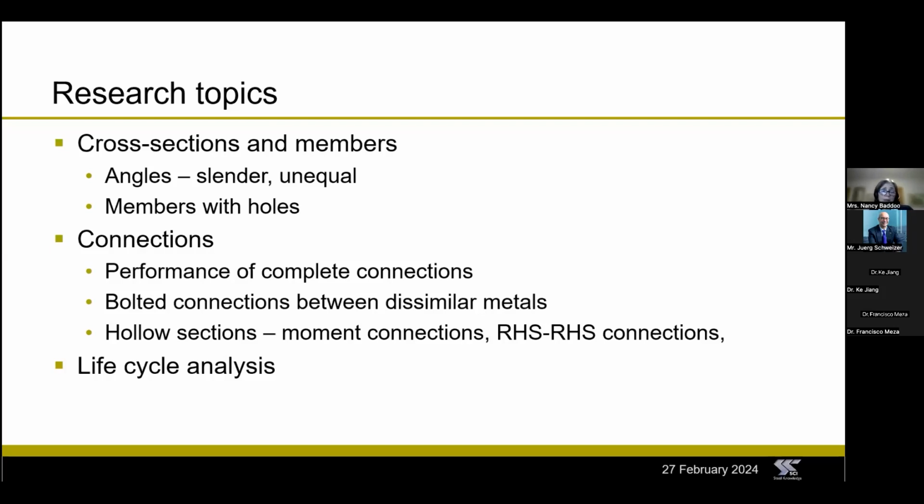There's work underway in the States, at Imperial College London, possibly elsewhere too. Stainless steel, you may remember, has a very low thermal conductivity, so it's appropriate for some applications in energy efficient structures, and for these you sometimes have long slotted holes, so that's another area where research is needed. Of course, connections: there are quite a lot of possible research topics still needing work, such as complete connection performance, and connections between carbon steel and stainless steel, where stainless steel is often bolted or welded back to carbon steel.